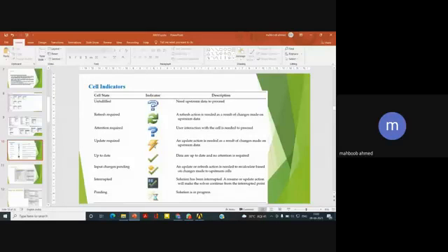If you are getting this thunderbolt sign, an update is required. Update is needed when you have done the solution but sometimes it wasn't detected, so it shows the thunderbolt sign. A green tick means no attention is required and your analysis is up to date. A green tick with a yellow upward arrow means either an update or a refresh is required.